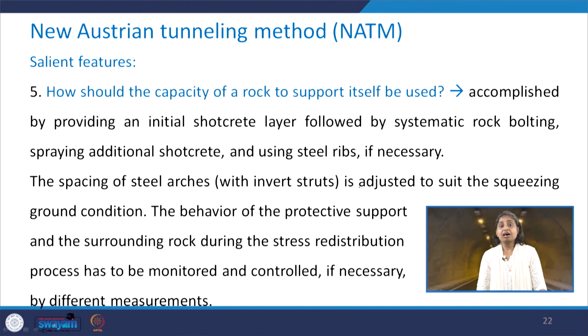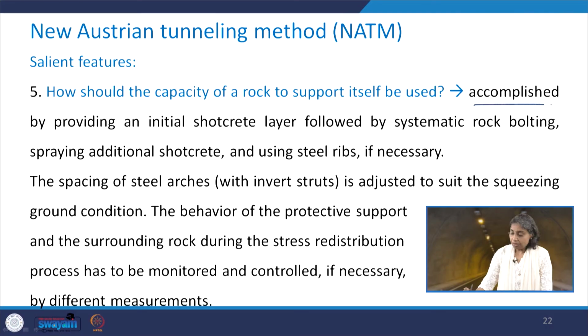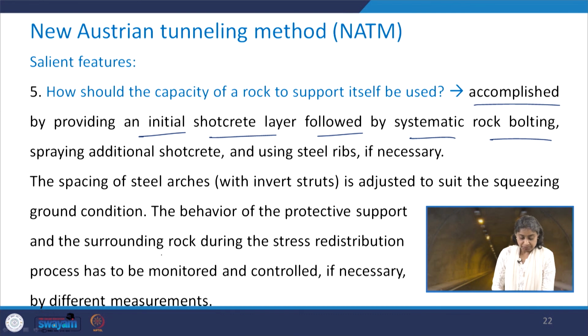Now the question is, how should the capacity of the rock be used to support itself? That is the principle of the philosophy of NATM, that it should be the self-supporting load member. This is accomplished by providing an initial shotcrete layer followed by systematic rock bolting. In this case, spraying additional shotcrete and the use of steel ribs may also be there if necessary.